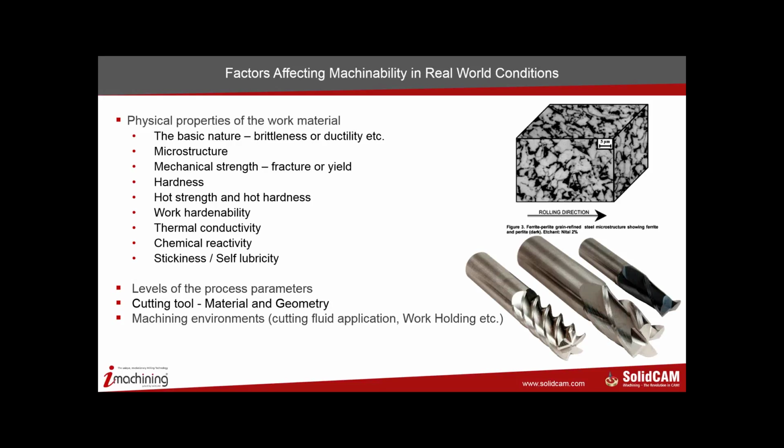Why? Because stainless steel, like we saw in our slide before, has got a much poorer machinability than AISI 1112, which is also a steel and probably would have a similar tensile strength. So it's important for us to determine the exact machinability of this material. And to do that, we have got a very simple test that you need to run.